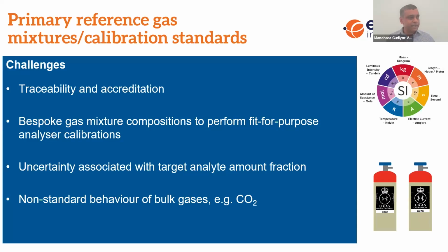The other challenge, the biggest problem in developing this primary reference material calibration standard, is that many people can come forward and say, okay, we can provide these calibration standards. The question we need to be asking is whether they're traceable and whether they're accredited. Certified reference materials, if they're not accredited, are as good as not using them. Another challenge is that the compositions are really complex and bespoke, so we need to make sure we develop fit-for-purpose samples used for analyzer calibration as well as for validating our results.